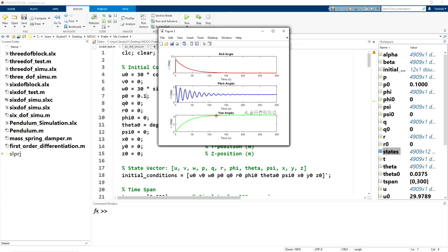And xi, actually we don't care in which direction the aircraft is heading. Theta, actually, is important. Theta is approximately around 1 degree. Here we have velocity again approximately 30 meters per second. Alpha is again approximately 2.14 degrees, and beta also goes to 0.